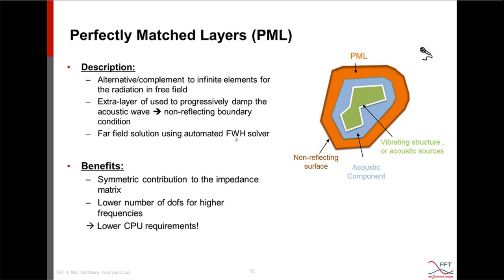There are some benefits of the PML method compared to the infinite element method. First, as we know in finite element analysis, there is an impedance matrix related to the finite element system, and when we have infinite element method, the impedance matrix is an unsymmetric one, and with perfectly matched layer method, that matrix is a symmetric one, and this consequently will lower the number of degrees of freedom, especially for higher frequency problems.